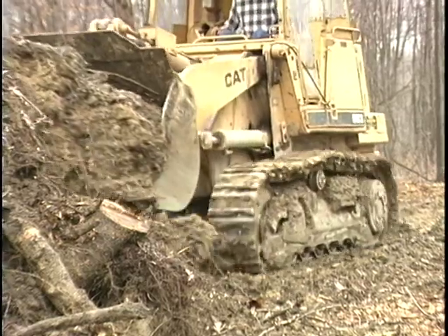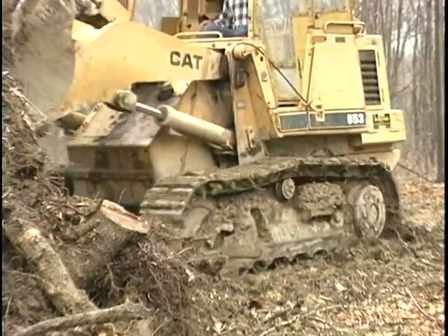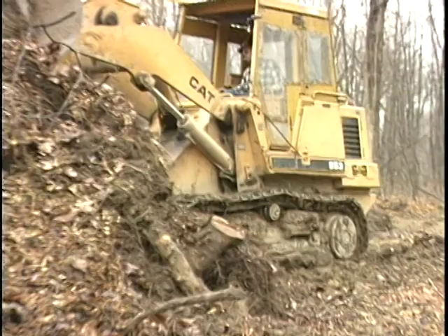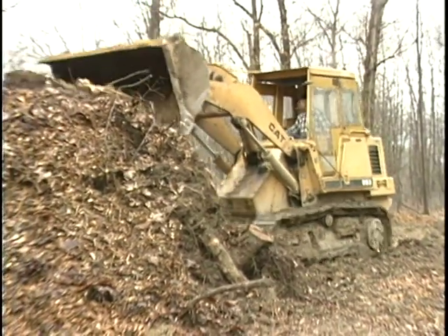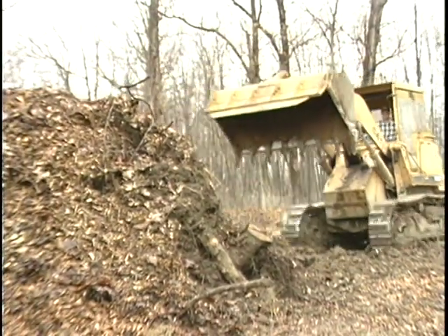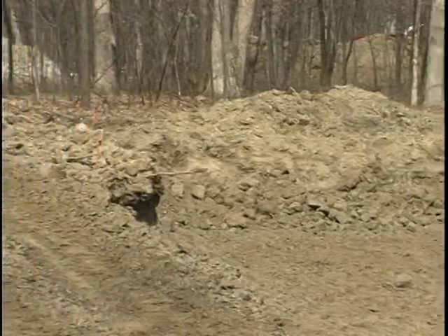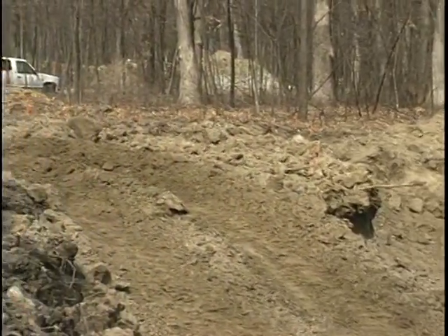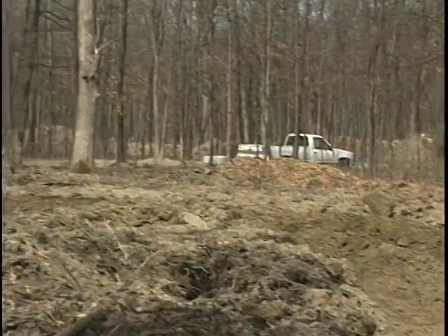Building sites on steep slopes or rugged terrain should be rough graded before the building is laid out. Topsoil should be removed and piled where it will not interfere with construction work. This topsoil can be used for the finished grade after the house is built.